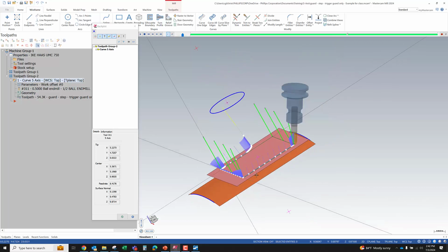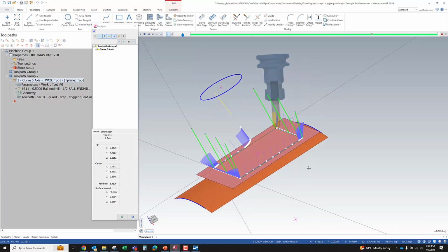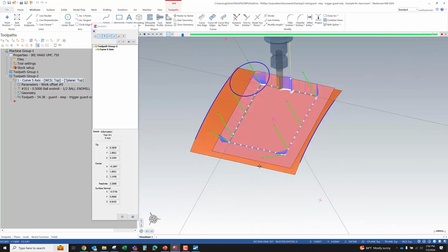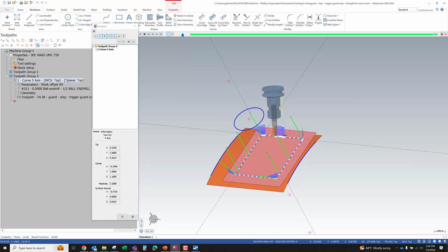But this is the table, just like tilting and rotating around, right? In this case, what we would typically see is the B-axis would kick over at negative 35 degrees. The tool would come down, and it's going to change in XYZ as that platter rotates around through 360 degrees or potentially a little more, right? So that's going to end. It's going to pop off there.